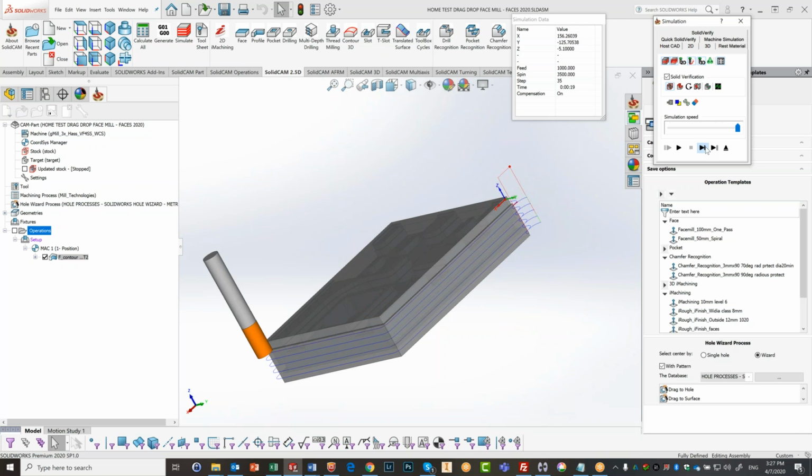Go around here as well. And when it finishes, now it's going to arc out. Now we jumped up. Okay, you may ask, all right, why is it jumping up? As default, we have it go to its clearance level before it goes to its next step. The reason for that is, in this particular case, it's at the exact same spot where it started off from.